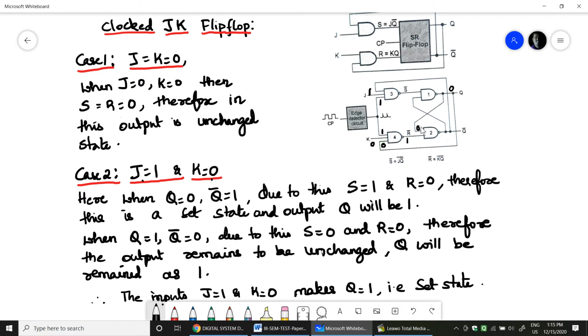and this 1 and 0 is given to this input of this NAND gate, and any one input is 0, again this will be equal to 1, and this 1 is now given to this, and this same 1 is again given to this flip-flop, this NAND gate. So when all three are ones, the output of the NAND gate would be equal to 0, and 1 0 will again give 1. Therefore this 0, what was the initial state, has now become 1 again. So in the JK flip-flop, if you see, when both are 0 0, there is no change.